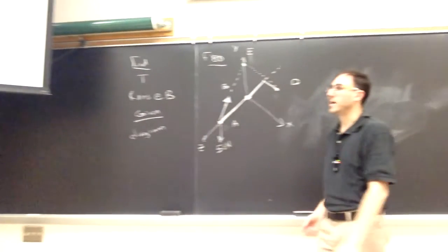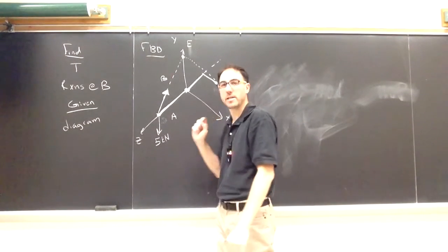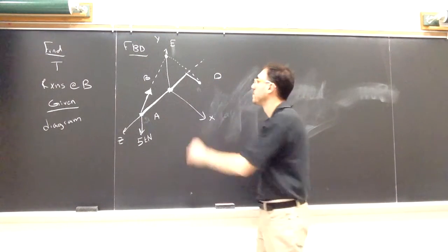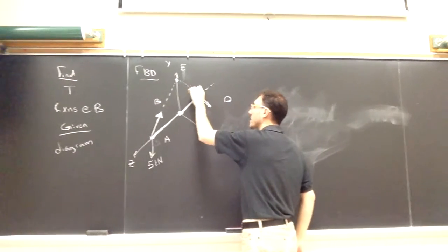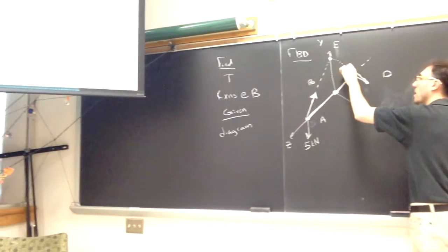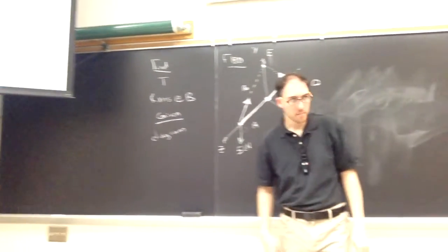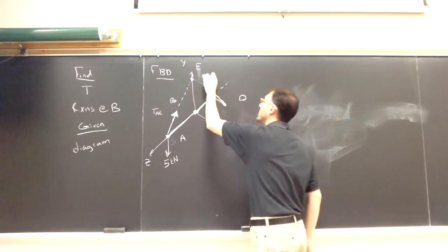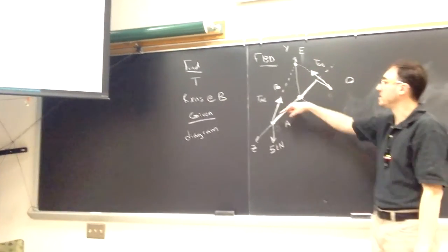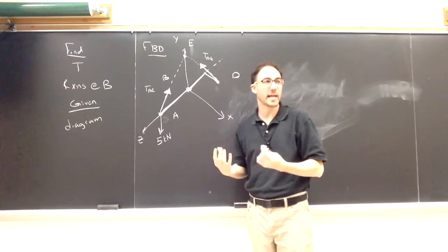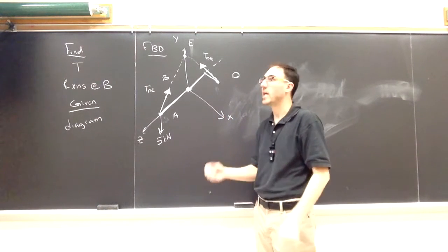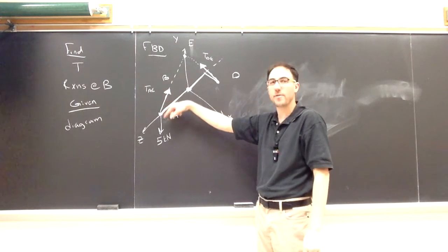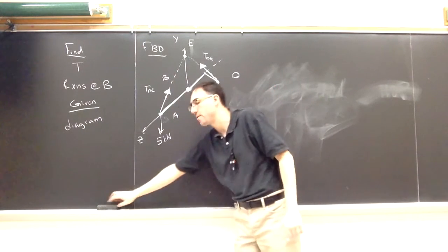What other force, or forces, act on the object that I decided to keep? Right. Another tension from D to E. So there's a rope pulling from D to E. What do I know about these two tensions? Right, their magnitudes are equal. I could have labeled this TAE. I can label this TDE. However, because it's the same rope going around a pulley, when we're in static equilibrium, the tension in a rope is constant even when it goes over a pulley. So actually we know that the tensions of these two forces, even though they're in different directions, their magnitudes, or their values of tension, are equal.